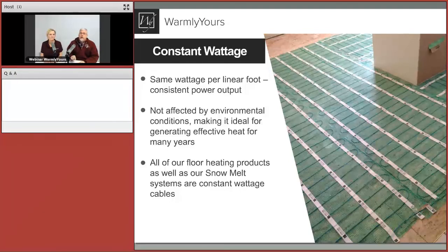The thing about constant wattage, compared to self-regulating, which you can cut wherever you want and make whatever length you want, as long as you don't go too far, is that this product depends on every foot of that being intact. So you want to make sure that you never, ever cut the wire, and that's exactly why. And I would say the reason we chose constant wattage and lead with it is because it has a much longer life than self-regulating. In our mind, there are definitely applications for self-regulating, and we support those, but indoors for floor heating, constant wattage is the way to go.